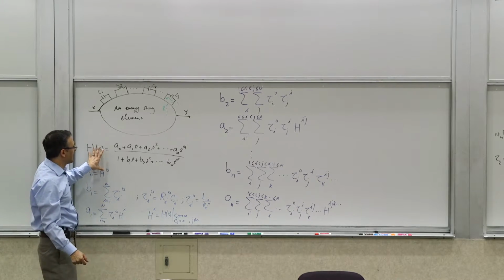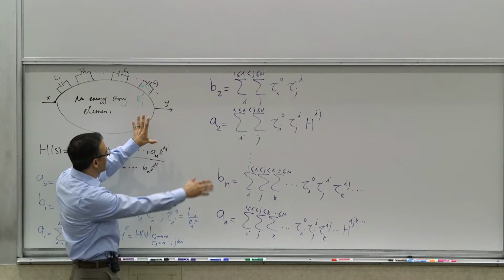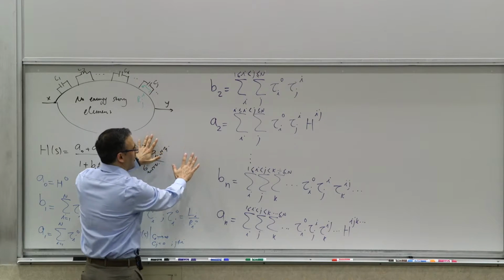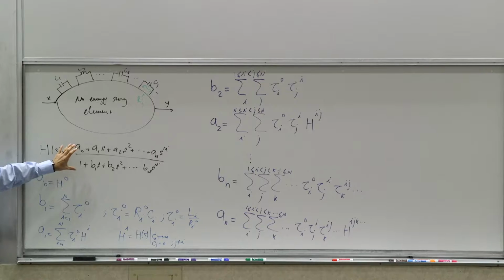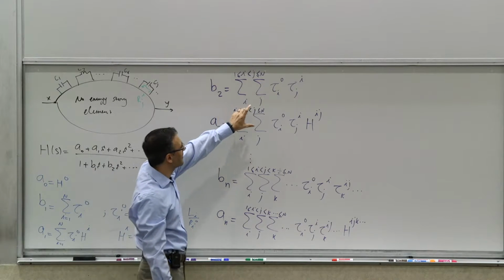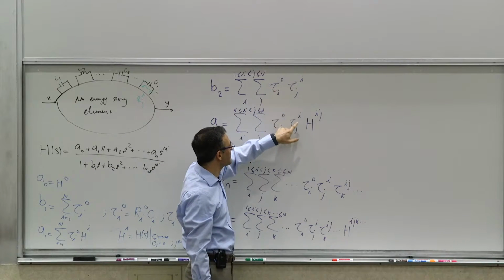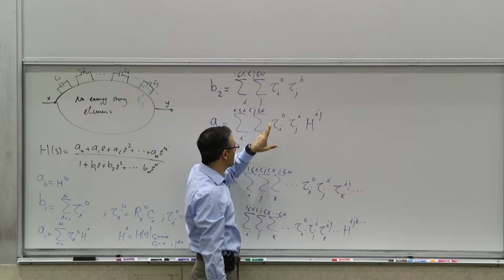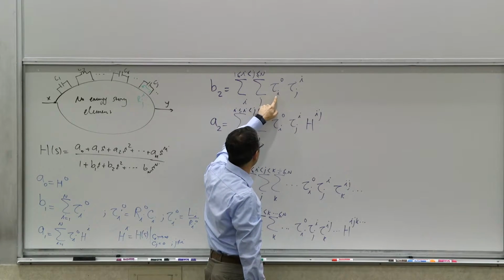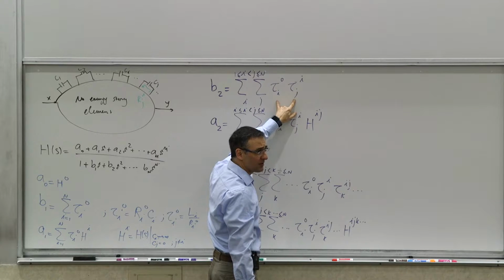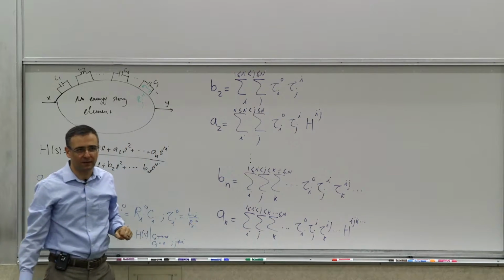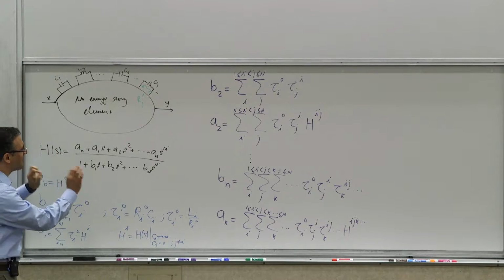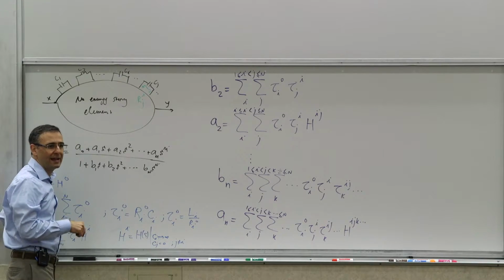Okay, before the break, we did the full derivation of this, the generalized time and transfer constant. So we saw that all the terms of this transfer function can be calculated exactly using a combination of time constants and transfer constants. To refresh your memory on the notation, the subscript is associated with the element, and the superscript is the indices of the elements that are infinite valued.